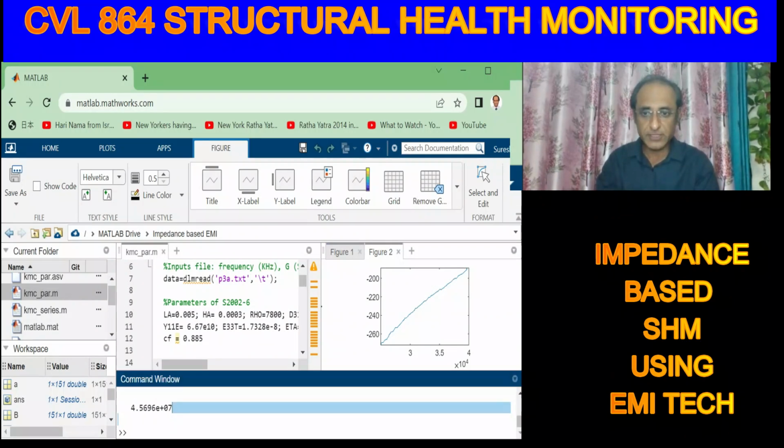I hope you can read this figure? 4.56 into 10 power 7. So this is the reduced stiffness. So this is the impedance-based identification. So here we are not relying on the visual change, but we are relying more on a very specific parameter, the stiffness. Also, this is better than the root mean square deviation, which is non-parametric in nature.